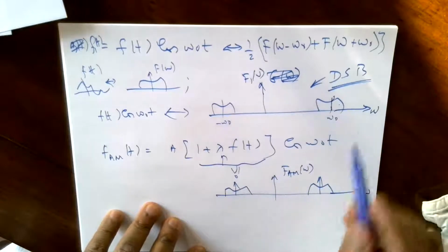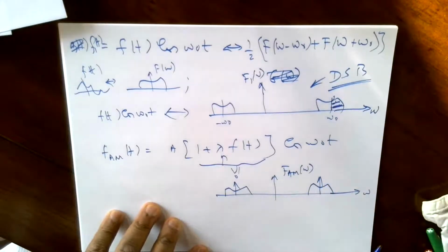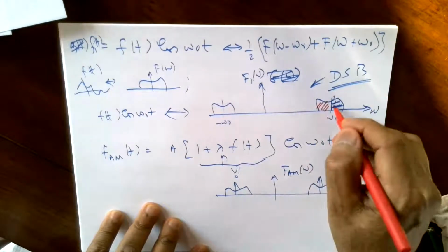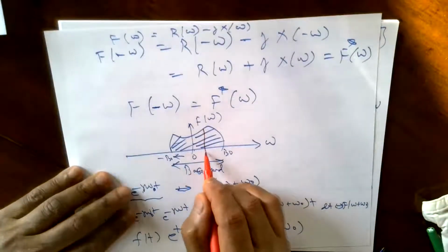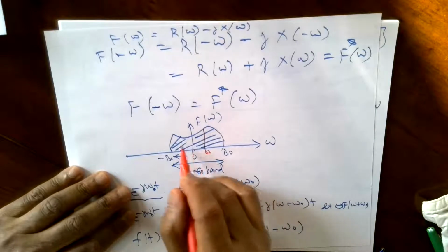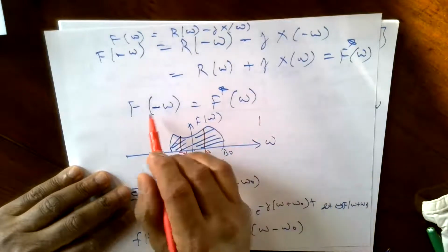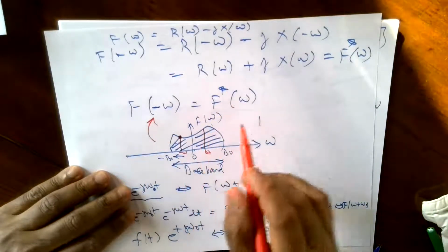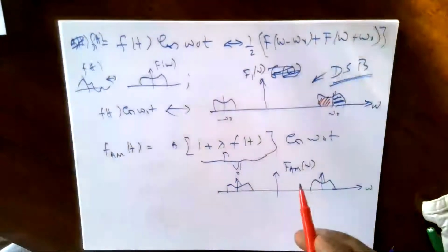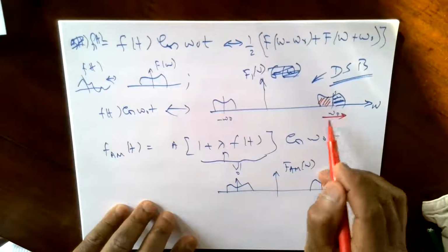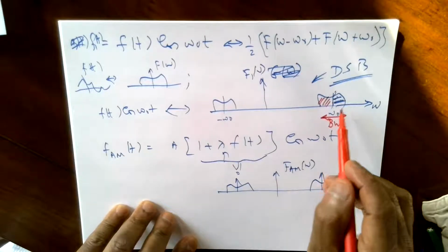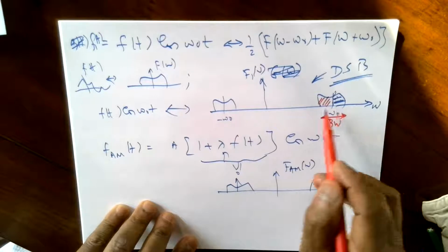Notice that previously I said if you look at the information here and the information here, they are the same, because you can obtain the one from the other. This information here, if I call this some frequency ω, then the corresponding information at minus ω is obtained by this relation. So the value here is simply the complex conjugate of this. In essence, when you duplicate, you are occupying this much bandwidth, but only half of it is needed, it's actually duplication of information.